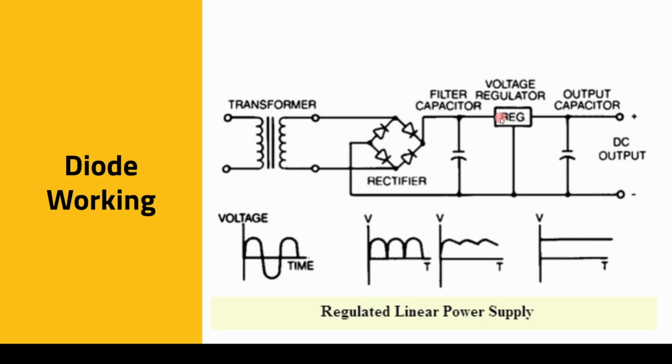So then you give that as an input to a voltage regulator, whose purpose is then to smoothen out and make sure that you get a really nice, clean, direct voltage output. So that's a look at some of the components that we've already looked at in our past sessions up until now. You will also have additional capacitors on the output for the same purposes of smoothing and filtering.